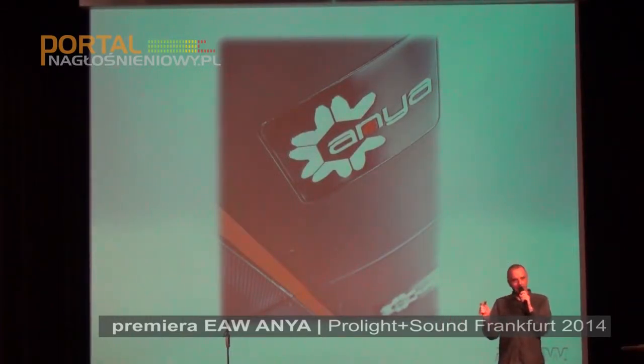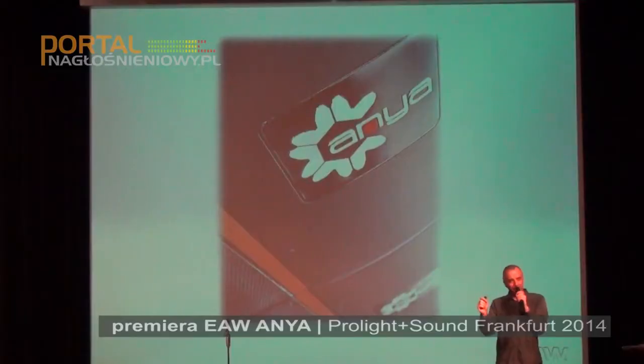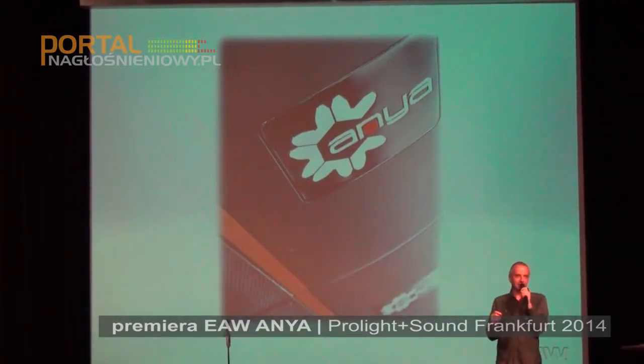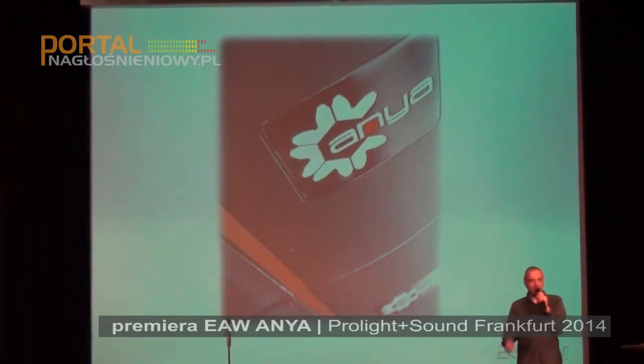Once you've changed the device, you can now test it against the original curve from the factory. And that will give you a plus or minus pass on the new device. Once it passes, you can now overwrite the old frequency response curve and store a new curve for that particular device inside of Anya's memory. So this is the way to keep your equipment up to date and keep it up to snuff.